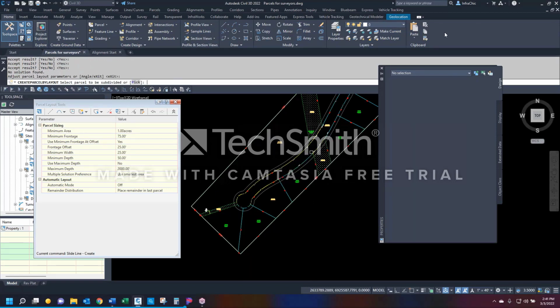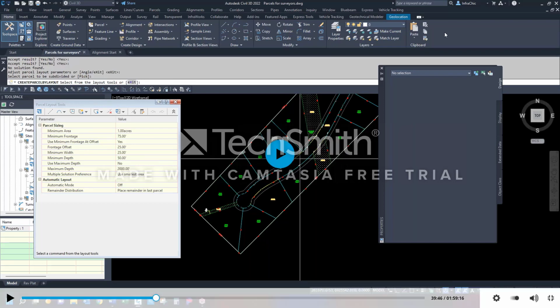Last one. Now this is the one I've had a little problem with in the past, so it may be a little weird, but we're going to give it a shot either way. Select the label. Come over here to the drainage easement again, say end, and go to the pipeline easement end. Yes, enter. Yep, beginning and end looks good. Enter, enter, enter, enter. This is the one that's weird. Okay. Now,